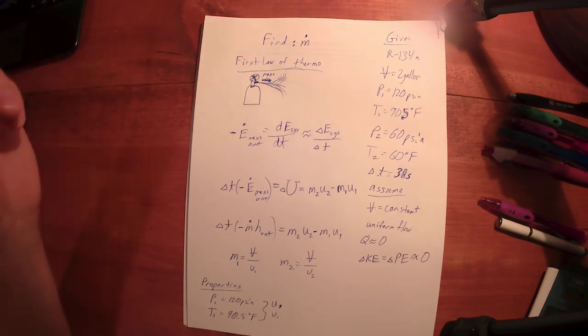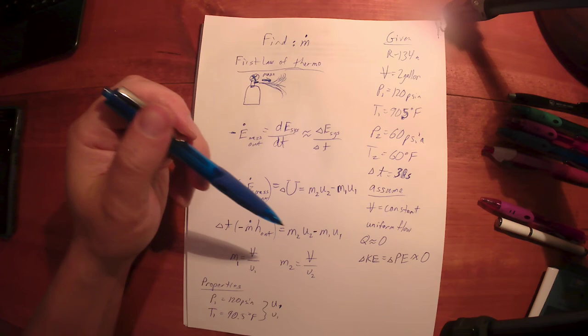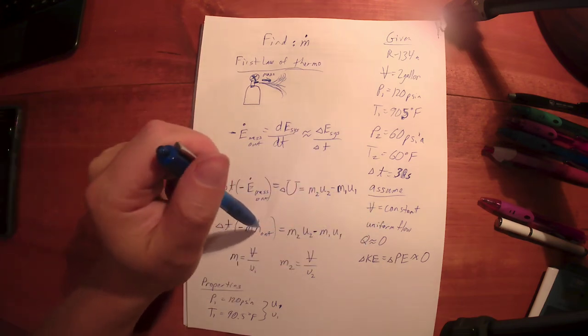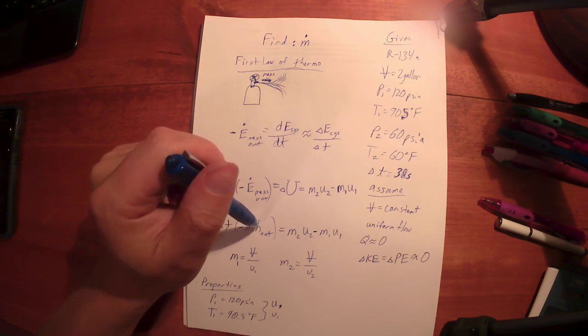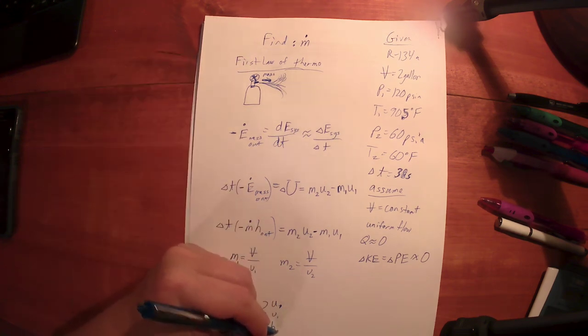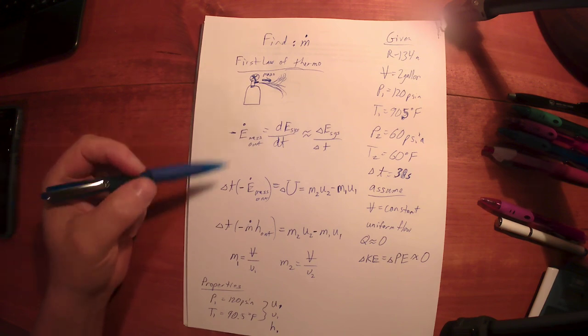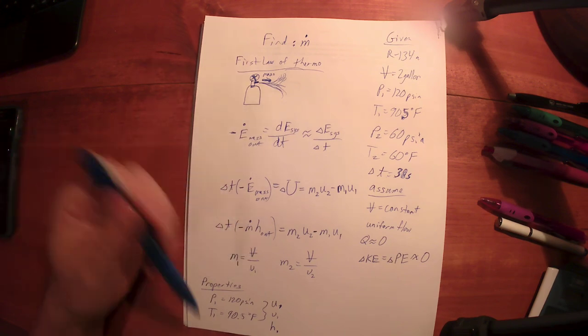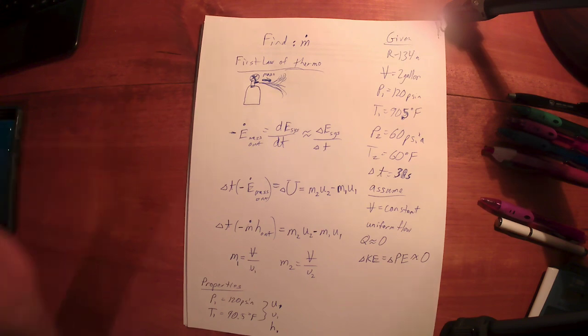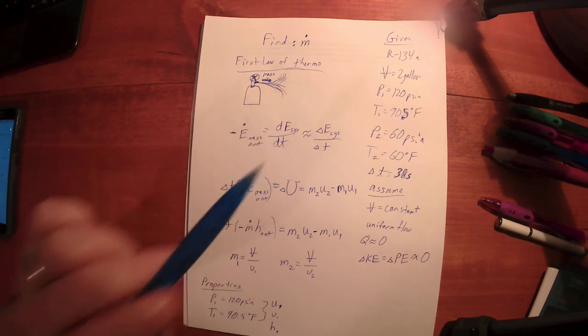Some would suggest that since you're assuming uniform flow, you assume that the properties stay constant the entire time. So it starts out at one value and it stays that h value throughout. So you'll see a lot of solutions will just tell you use that h value. I always suggest, well, why don't you just look at h1 and h2 and see if an average makes sense, or maybe solve it with one h value, solve it with the other h value, and then report a range. And I think any of those are okay because, again, we're doing an estimate.